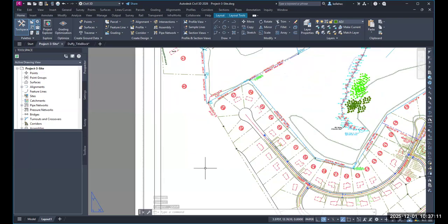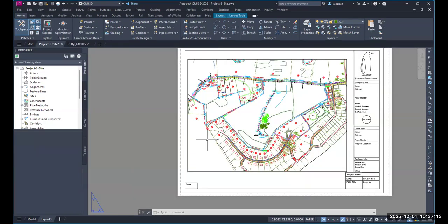So as a reminder, you can create that in here, in layout space, or you could create that in model space. It's up to you. You can still use the same features over here in layout space as in model space. So if I do dtext, I can specify the start point of my text. I can specify my rotation angle. The text is coming in really big. Oh no.